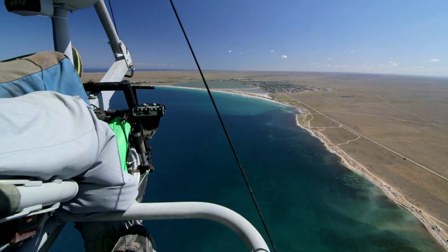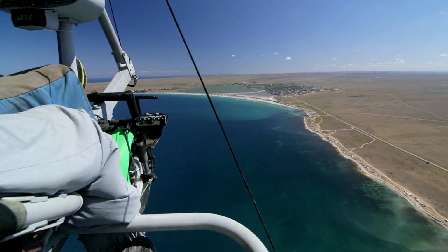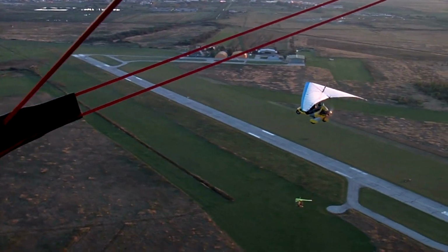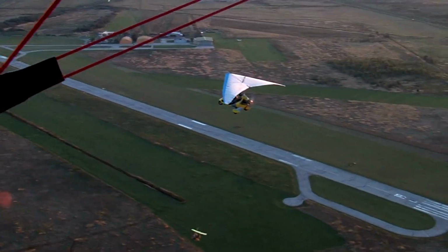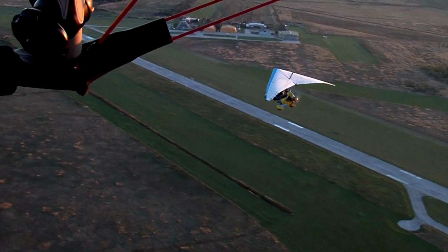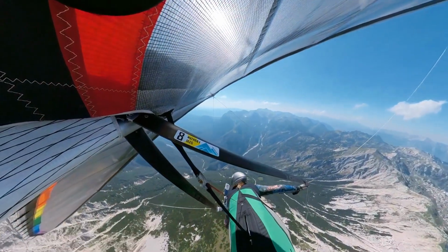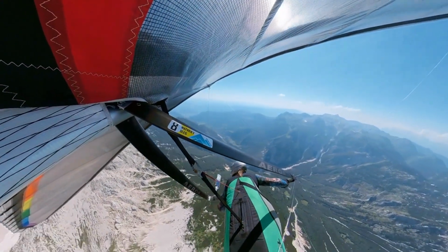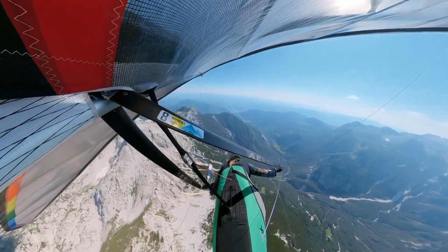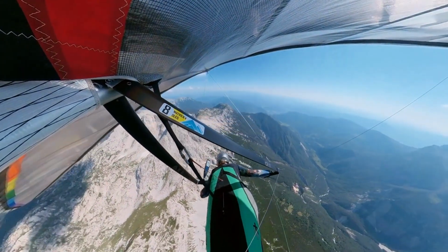Parasite drag is influenced by the friction of air over different aircraft components. Similar to lift, it escalates with the surface area of the aircraft and significantly rises with airspeed, following the square of the velocity. Streamlining elements, like round tubes and cowlings, can be employed to reduce parasite drag, though this incurs additional costs and adds weight.